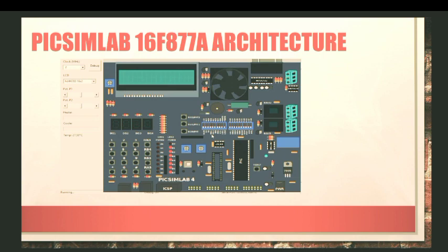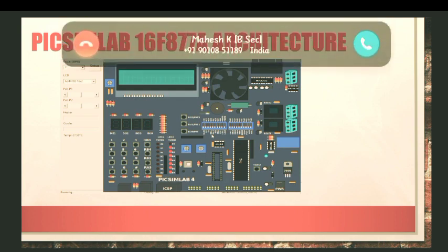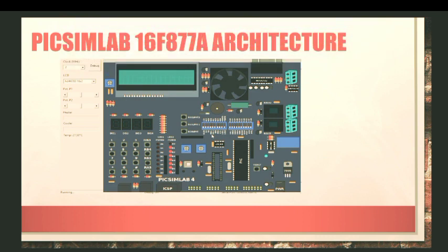An interrupt is a communication process set up in a microprocessor or microcontroller, in which an internal or external device requests the MPU or MCU to stop the processing. Then the MPU or MCU acknowledges the request, attends to the request, and goes back to the processing it was interrupted from. There are hardware and software interrupts.